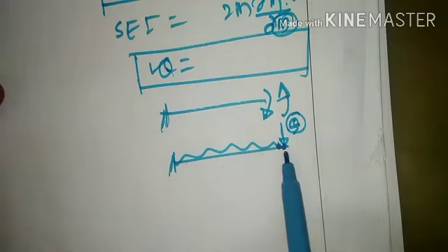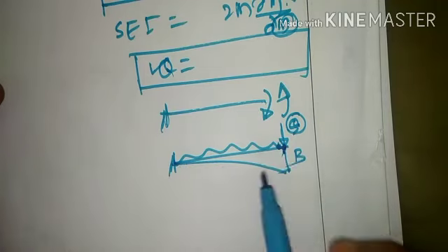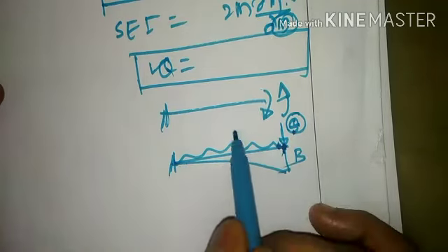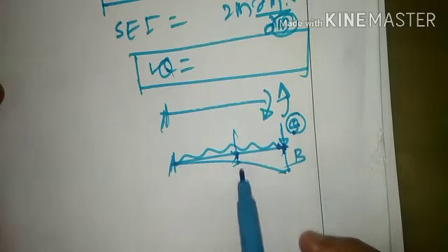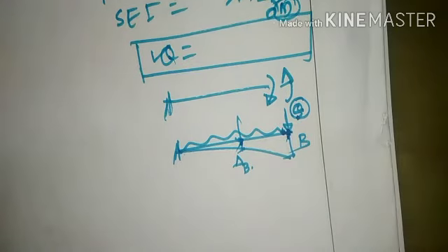If I impose the fictitious force at the free end, the deflection is calculated at the free end. If I impose the same fictitious force at the mid location, then the deflection will be calculated at the midpoint of that beam. If you already have a point force, then there is no need to put any dummy force in that situation. We can straight away consider it in the equation and then partially differentiate it. If we don't have one, then we need to impose a fictitious force and then continue with the solution.